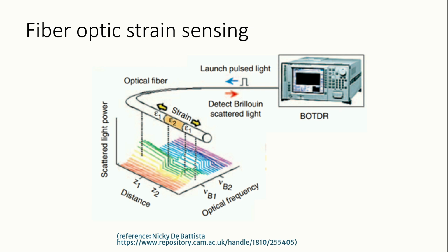The other type of technology is optical frequency domain reflectometry, or OFDR, that measures phase shift in the fiber optic and offers a higher spatial resolution. We're talking about sub-millimeter resolution, and it is able to make dynamic measurements over shorter distances, about 100 meters, and the one that we are using is 50 meters, which for a structure is something that we can use.